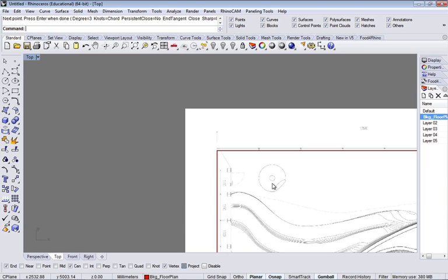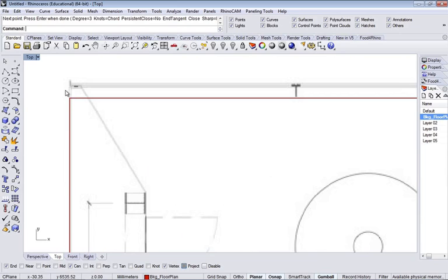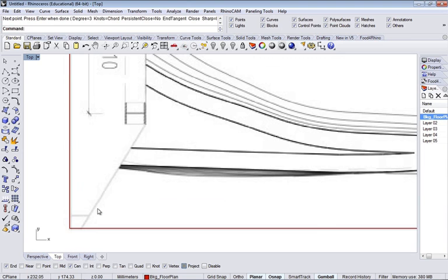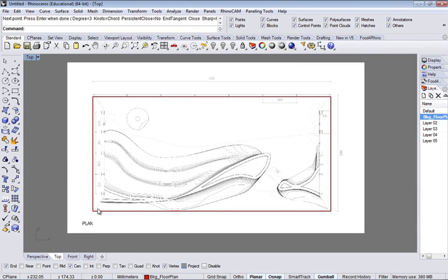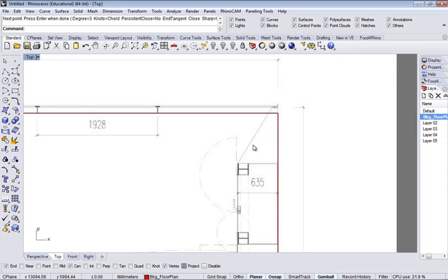And I want you to pay particular attention to these corners here, how this is built up. You can see that it's not a sharp knife corner, that it doesn't meet that corner nicely. So this is where paying attention to detail really pays off, okay? And that's where I want you to start, is get the rough shape modeled with good detail.